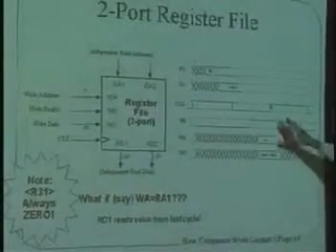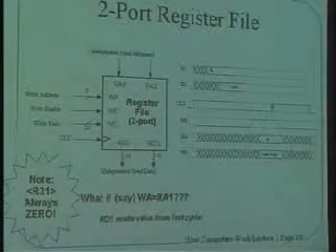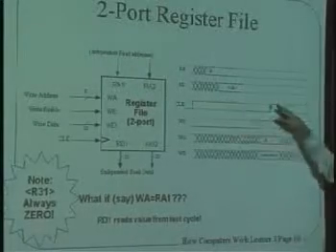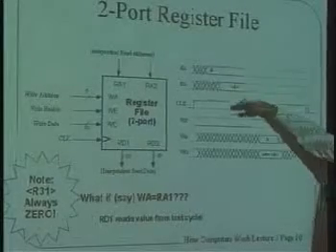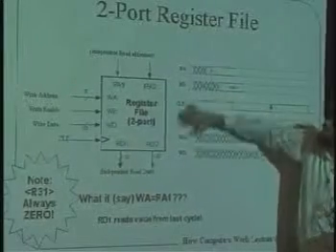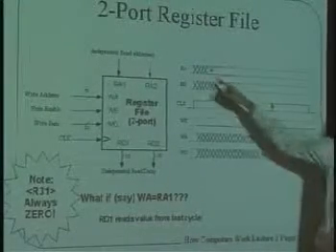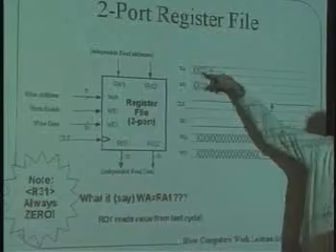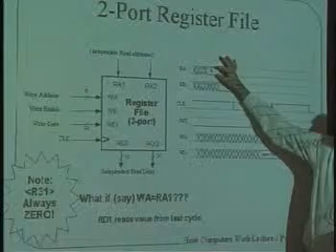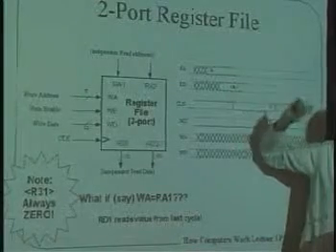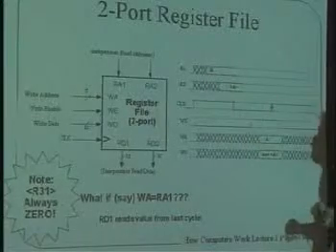Let's take a look at the timing diagram now and see if we can understand how this goes. First of all, the clock here is going on and off and on and off, but that has nothing at all to do with what's happening in these first two lines. So I want you to think about all this stuff down here as not making any difference for the next minute or so. RA has some indeterminate value that we don't know, and then finally it settles down to either a high or a low on any of the 32 bits that it has, and the value that it has is A. A is an address.